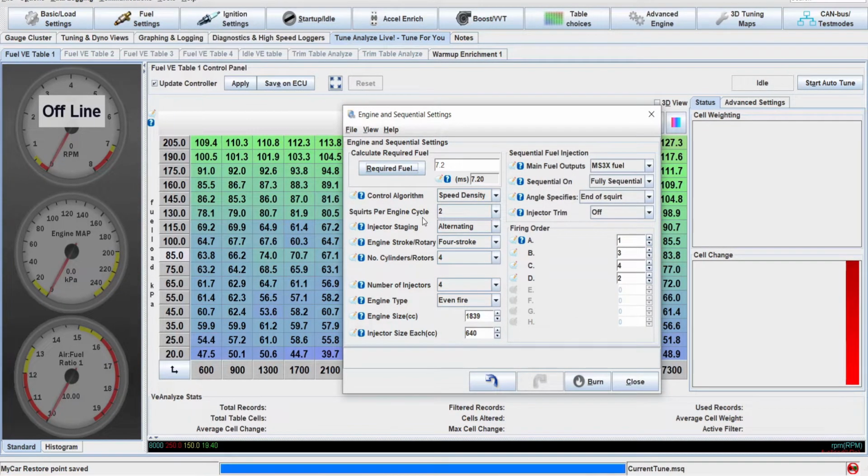Two problems though. If you're converting to E85 and will never switch back, this may be an option. If you plan to switch back and forth, don't do this. You'll be constantly tweaking your tables, and it'll never feel quite dialed in like it did on one fuel type. Second, E85 is not E85. The ethanol content varies wildly, and I mean wildly, between stations and over the course of the year, especially in places that experience freezing temperatures. This is because E85 sucks in the cold, and they add more gasoline to it as a winter blend. So this option, while overall is super easy, it's still not ideal.